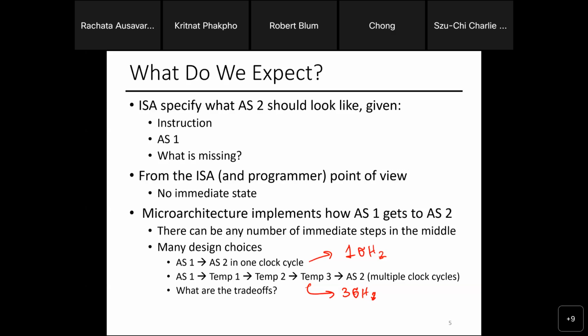My trick is 1 gigahertz. It means that 1 cycle is 1 nanosecond. It's 10 to the 9, and then you divide the whole thing by 10 to the 9, so nanosecond. 3 gigahertz means that 1 cycle is 0.33 nanosecond, so you get 3x speed up when you just do a lot of adds. And in that case, let's say I have to do the multiply for the top one, again, 1 nanosecond, so everything is 1 nanosecond, essentially.